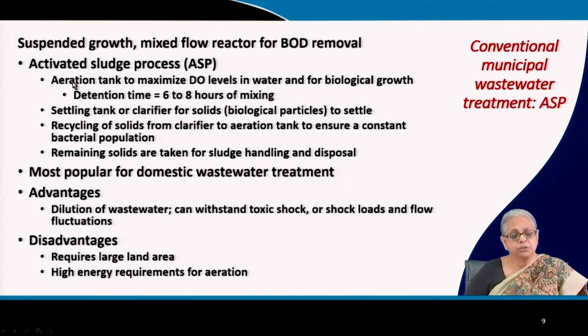So I've already mentioned that this aeration tank maximizes the DO levels. It can have a detention time of anywhere from 3 hours to 8 to 10 hours of mixing. And remember, the more time you provide, the greater the efficiency, but that also increases the cost of treatment. So it's a fine balance between the economy of the process and the efficiency of the process. So these two factors will determine what the practical detention time is.